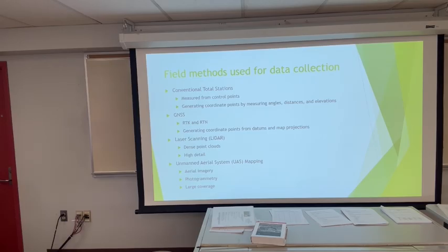Personally, I know things have gotten better from when I was out in the field regularly using this, but when I was out there, the Ohio VRS system was just kind of coming on and getting more and more popular. I'd set a couple points for control, then set up my total station and backsight. If I was within a tenth horizontal and 15-hundredths vertical, I was like, okay, that's as good as it's going to get. I'm pretty sure it definitely is getting a lot tighter. It also kind of depends on your VRS where you are in relation to a CORS station. The closer your distance, the better results you're going to have. The longer your baseline away from a CORS station, it starts getting a little sketchy.